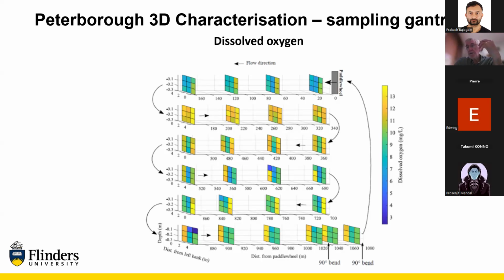Algae and other material got around the oxygen probe, and the oxygen probe was not reading correctly. We didn't recognize soon enough that the probe was not staying clear of contamination, and that depressed the oxygen values at the set point, and it caused this aberration here.